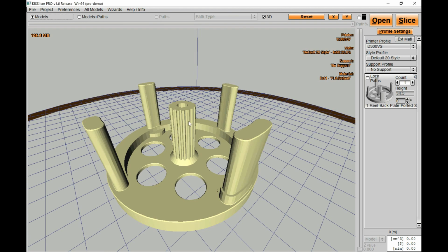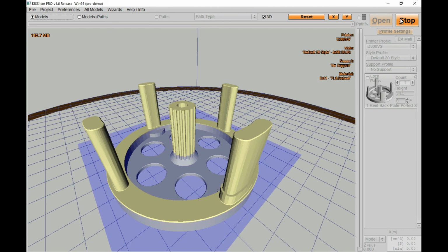These slender pillars on the part, and especially since there are 4 of them and then one in the middle, and you can see the one in the middle actually is like a little gear, are extremely difficult to print without getting stringing between the pillars and getting blobbing on the ridges of these angular. It's not actually a gear. They're there to minimize friction on it's a shaft and a spool rotates around it. And I wanted to use this to show you just how good the default parameters the wizards create are when we print this part. So we've loaded the part.